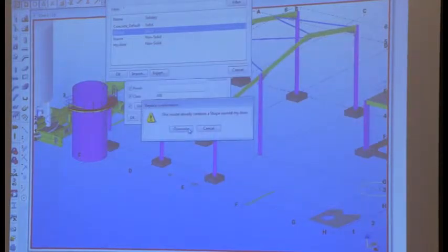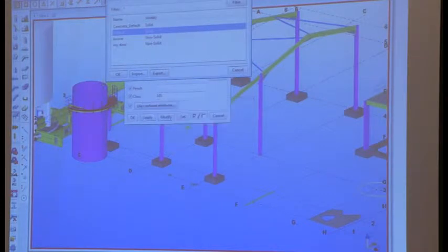Then it already exists, so overwrite it. I've done this for example. So what it does then, it takes that SketchUp model and converts it into a Tekla solid. Okay? Then we can say okay to that. So I'm now going to say shape, bring in my door, okay, apply okay, and then we're going to bring it in and say I want to put it in that point there to that point there.